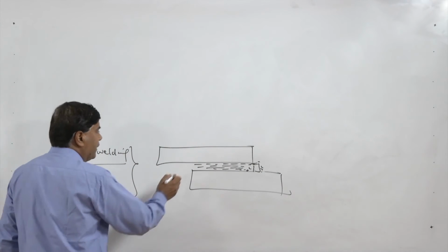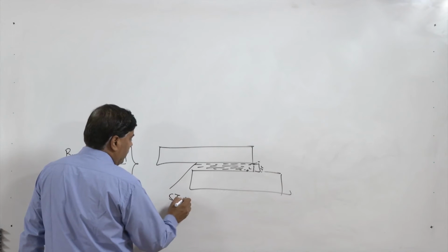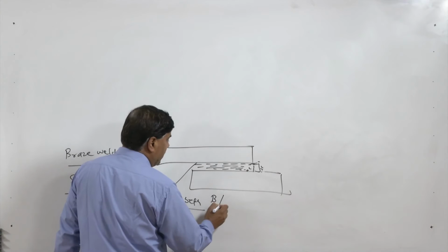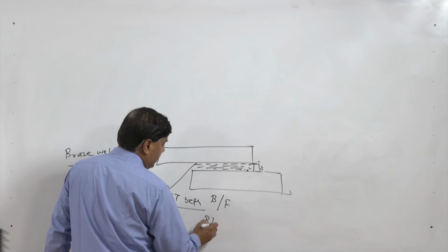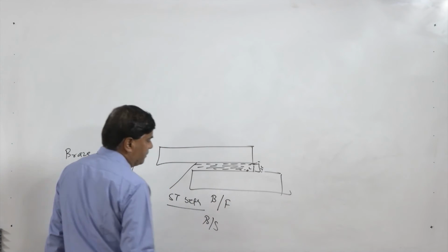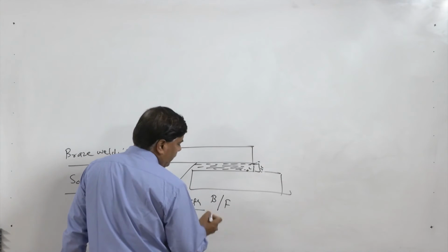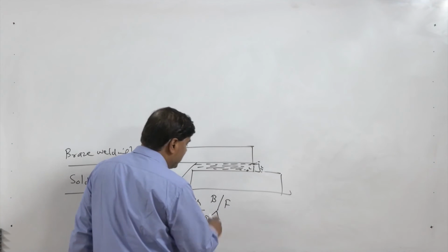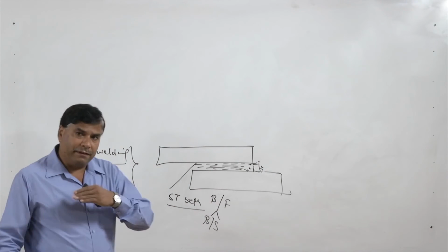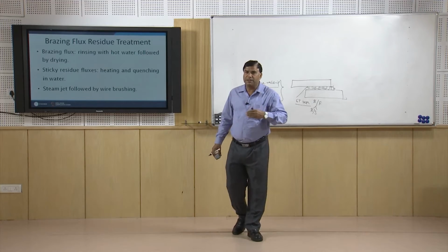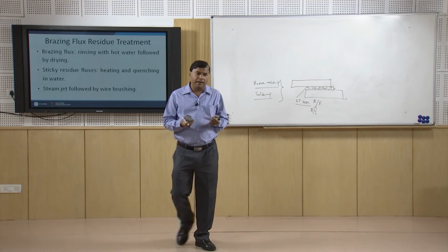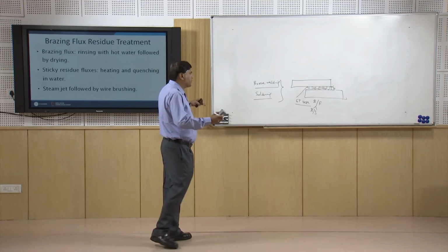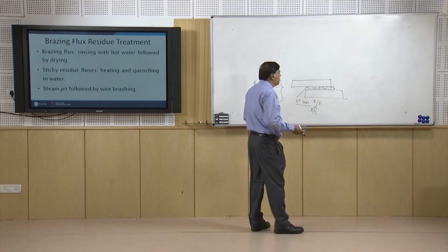So depending upon the surface tension between the base metal and flux, and base metal and solder, the surface tension between the base metal and the flux being lesser than that between the base metal and the solder, the flux is pushed out in the course of soldering, and the liquid solder will be pushing it outside while interacting with the molten metal.